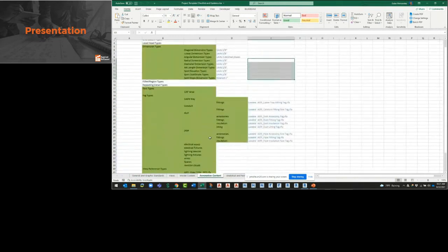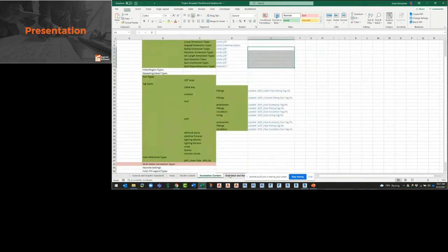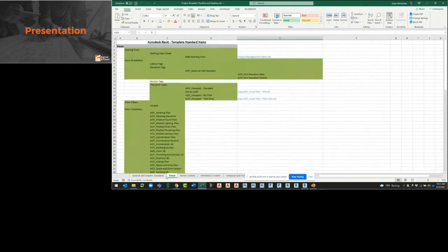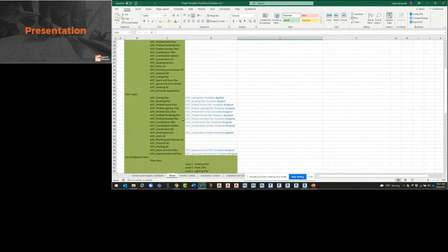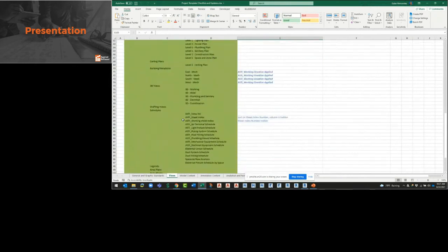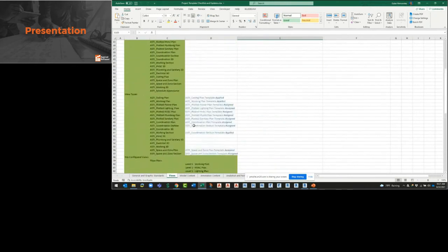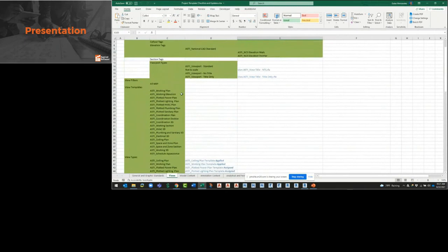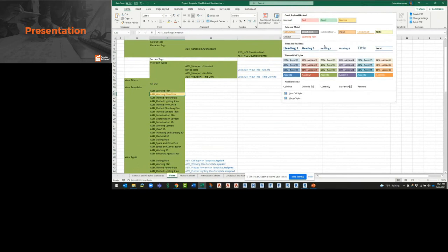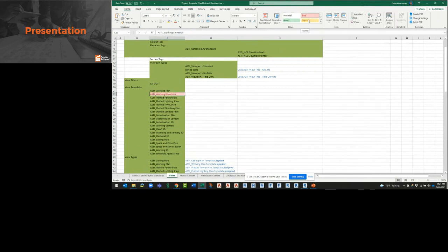In here, we'll create a spreadsheet in Excel of every setting that we have that's custom to the project, view templates and filters. These are just basic examples, but we'll document it all so that if any of that stuff changes, you can come back in, set it to a color code, maybe like neutral or needs input, or bad, maybe it doesn't work or something. And for the next project, we fix that or create a new solution for it, right?